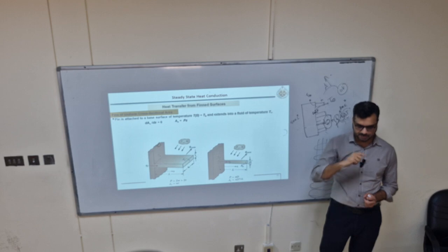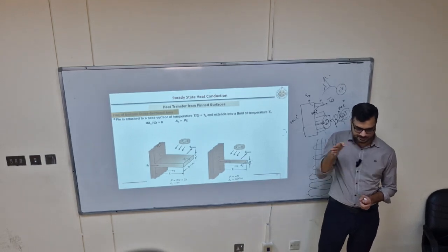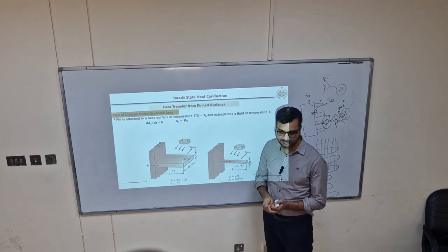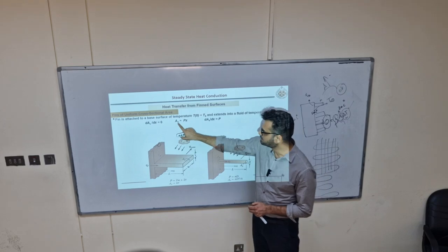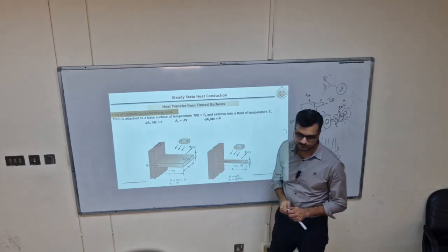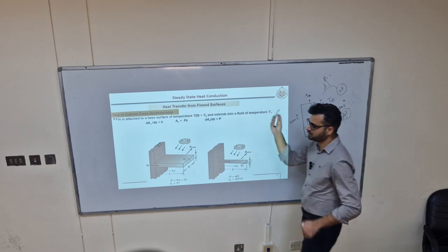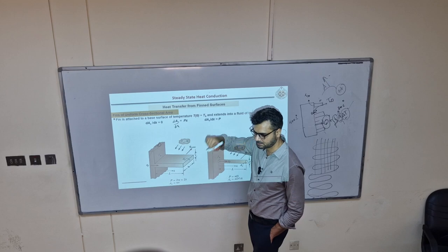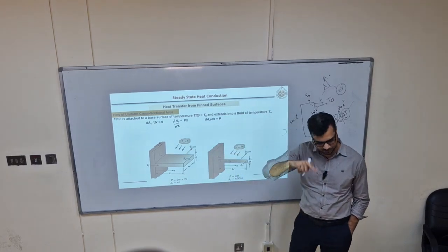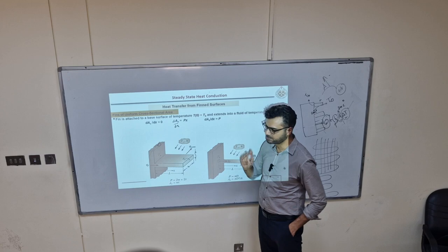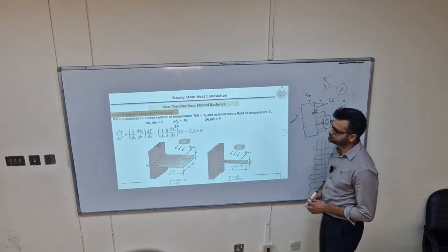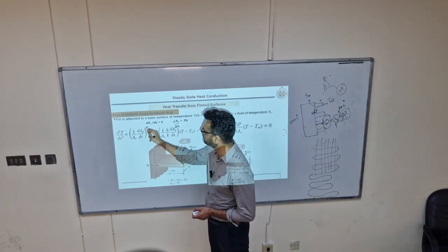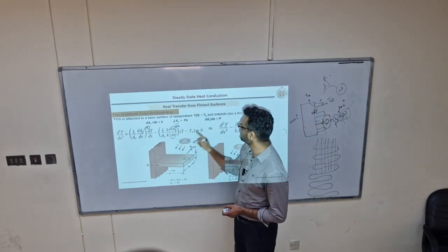Surface area is given by perimeter into x, so I can write surface area as P into x. In that differential equation we have dAs over dx, and d over dx of Px, where P is fixed for a constant cross section, is simply P. So the equation will reduce to this form because this term is 0. dAs over dx is simply P.